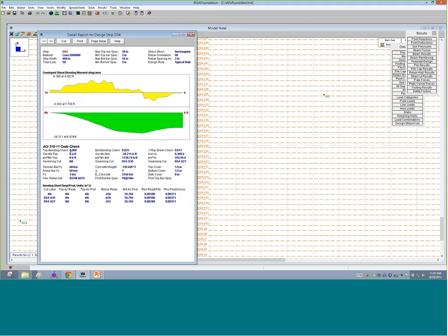And so the top check, there is no top bending, so we have zeros throughout there. The bottom check tells us DS4 X35 was the governing cut, and that's what the cut moment was found at that location. And then on shear, we have a one-way shear check, and DS4 X21 was another cut which governed for that check.